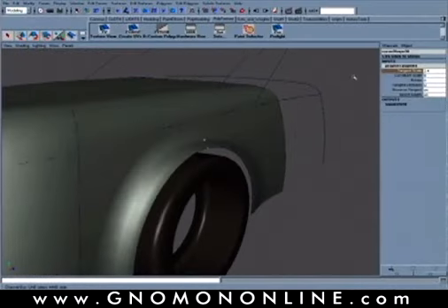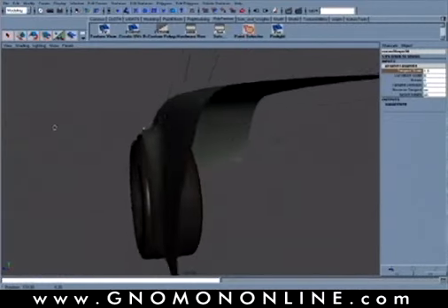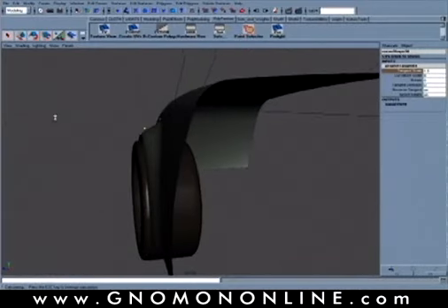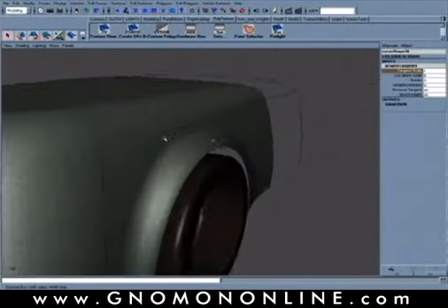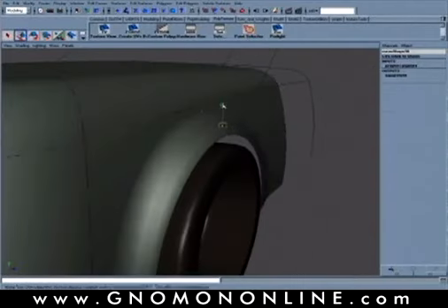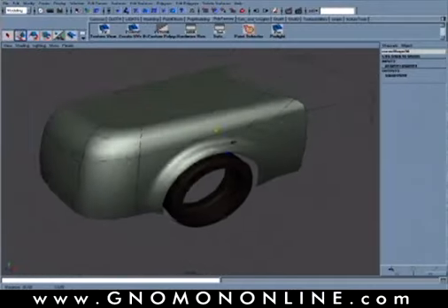So I'm scaling the tangent scale of that curve that I originally did my project tangent with. Again, you can see that that allows you to move the other end of that wheel opening so that you can flatten it out or create a really tight tangent or a really big loop there. And then you have the other curve again that you can manually go in and drag around to select how you want that arch to work.